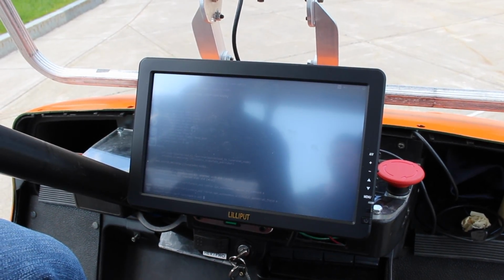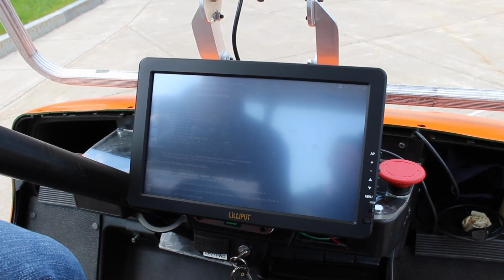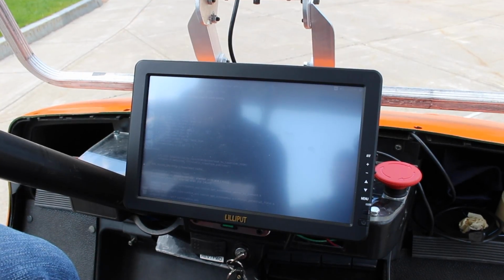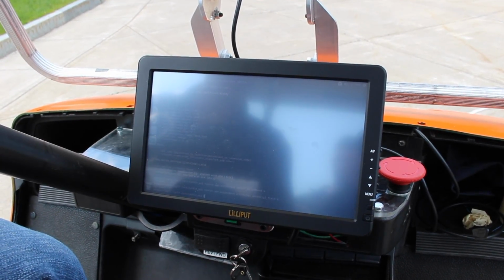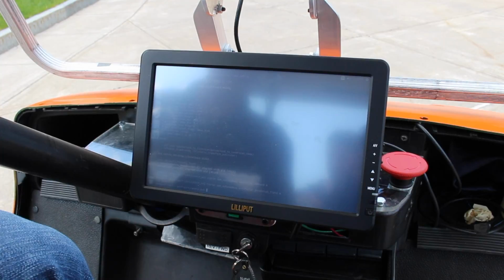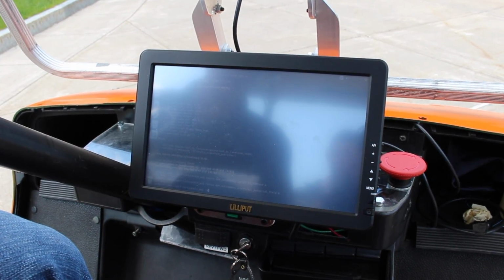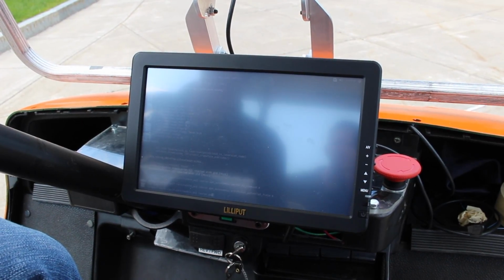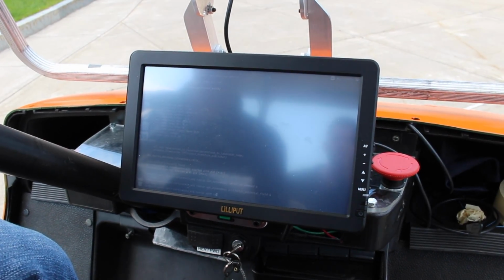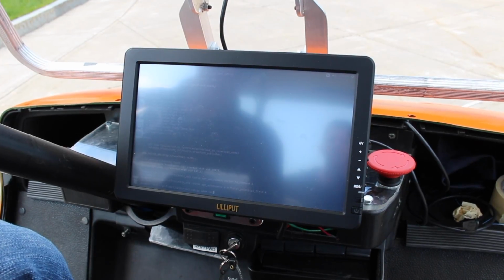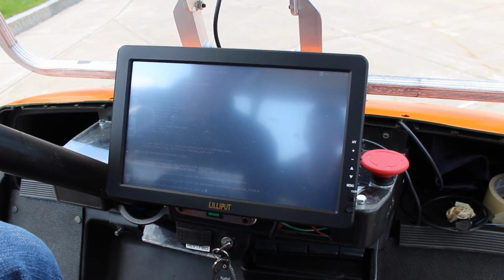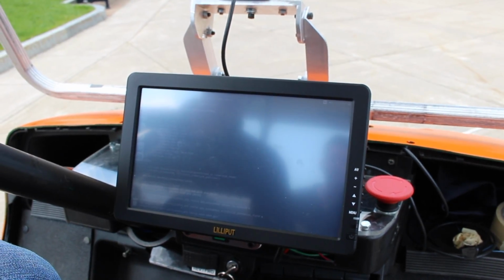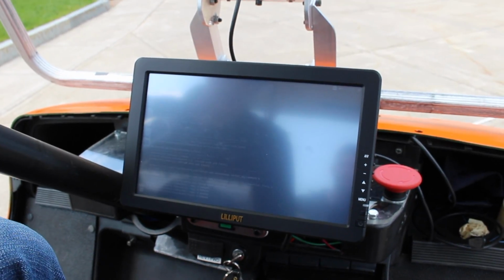So now it's time to run the odometry generation and the local driver. You're probably going to do those in two different tabs because they both output things. So here we'll do rosrun odom, and then odom_gen. And we're just going to leave that one not backgrounded, and this will start generating the odometry.